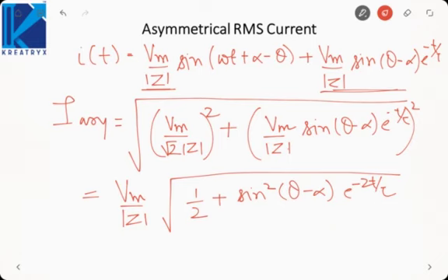See, if we open in the subtransient region, current will be highest. Then what will be happening? We won't be able to extend the arc that will be formed due to that high current. So we cannot open the circuit breaker in subtransient region because arc will be too dangerous. Then we cannot open in the steady state region also because steady state occurs after a long time.